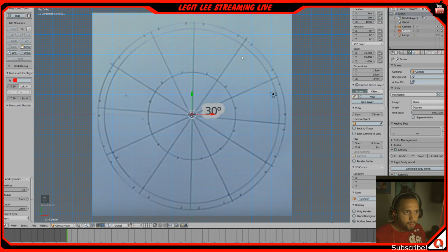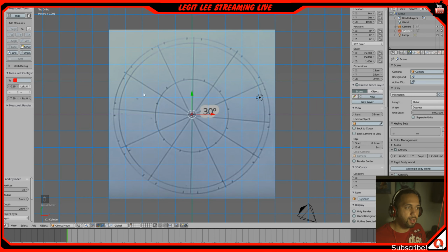So we have 1, 2, 3, 4, 5, 6, 7, 8, 9, 10, 11 individual cuts. Well, 12, I think, because I started from here. So 1, 2, 3, 4, 5, 6, 7, 8, 9, 10, 11, 12. That was my mistake. So we have 12. Now we need to make 12 sides. So how you do that is just change the vertices over here from 32 to 12. And there you have it.